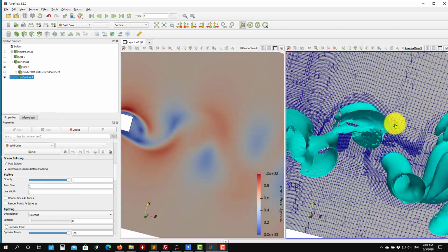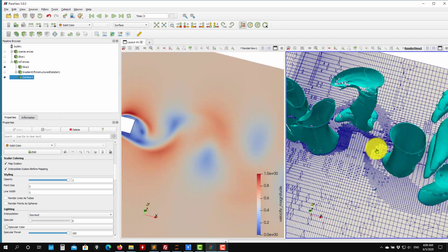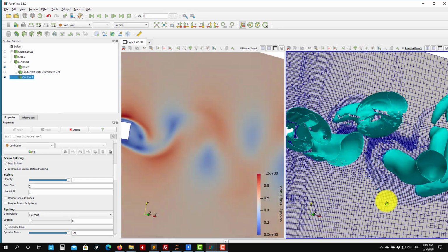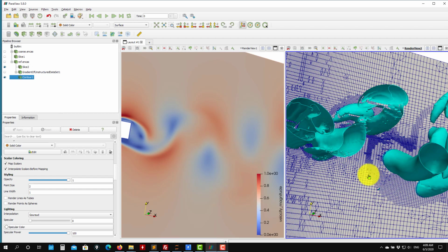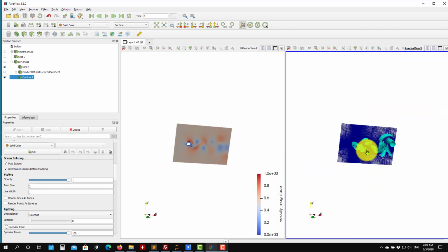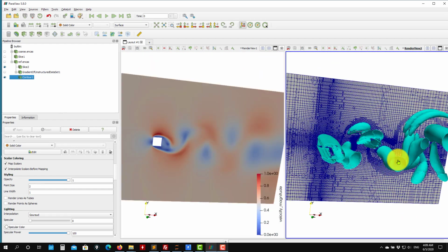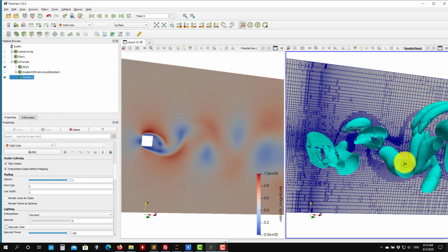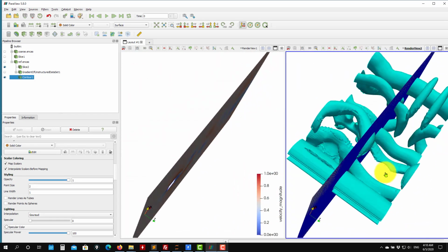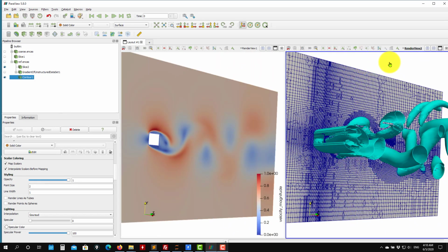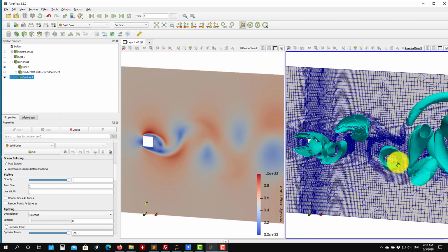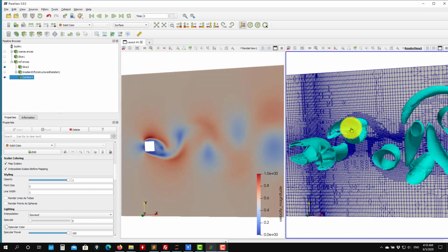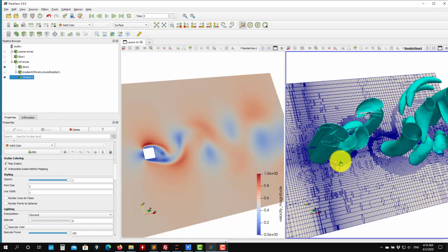But remember, it was a different refinement that we were using there, so it does not correspond to the Q criterion. Again, you can add a refinement on the Q criterion, and you can refine the result much better, and it can be adaptive, so each time it would refine. That is really expensive, by the way, but it can be done with no problem. So coarse mesh, fine mesh with the adaptive mesh refinement, and we compare the scales that clearly are different.